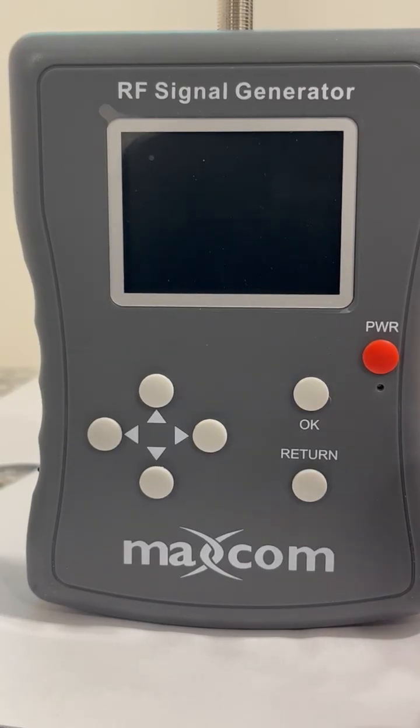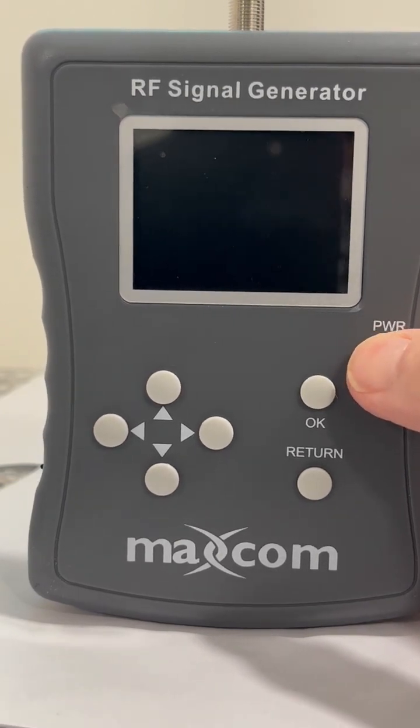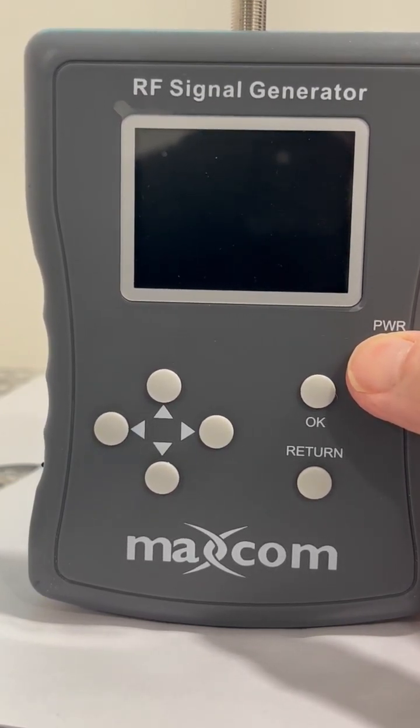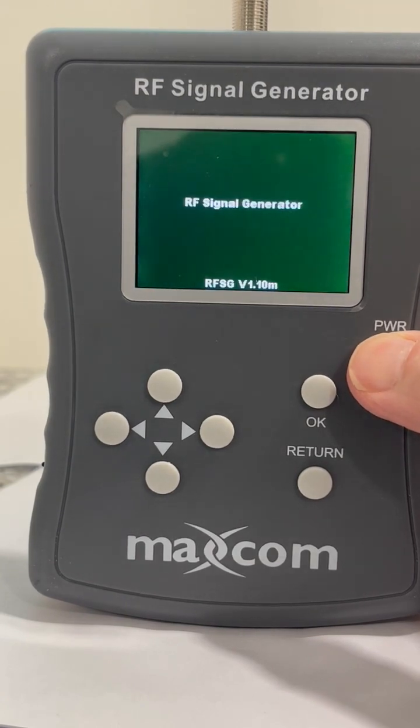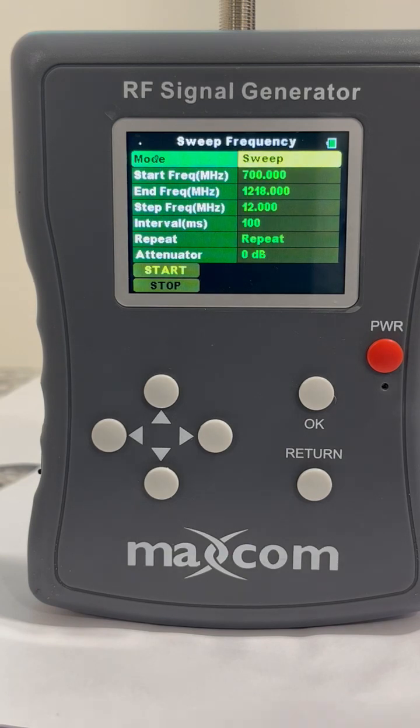This is the Maxcom RF Signal Generator, and we're going to demonstrate the operation of the tool. Starting with turning the power on, press and hold that red button, and it takes about 3 to 5 seconds, but then you'll see it says RF Signal Generator and it comes up. This is the last settings that were on there.